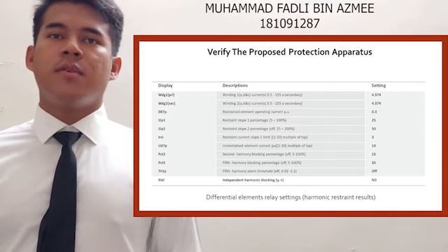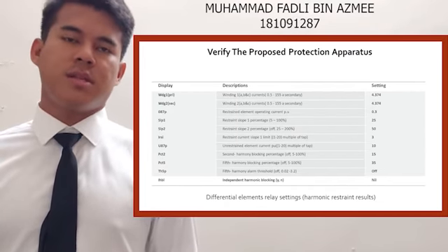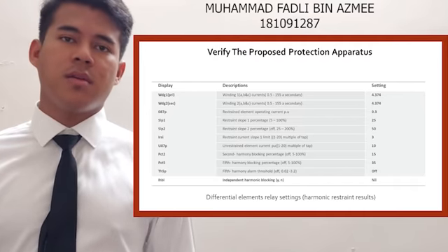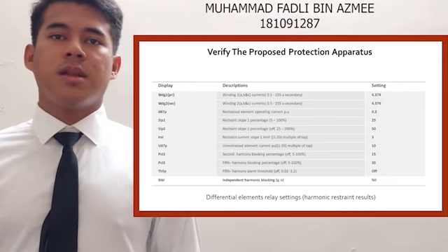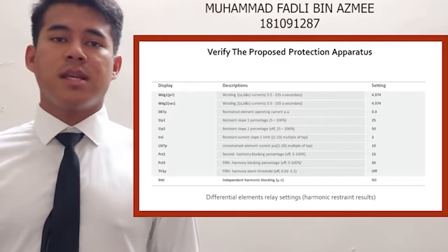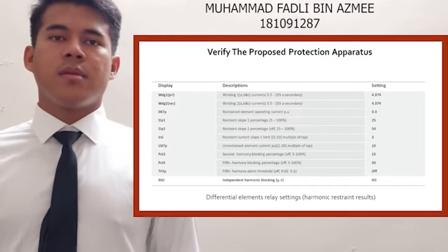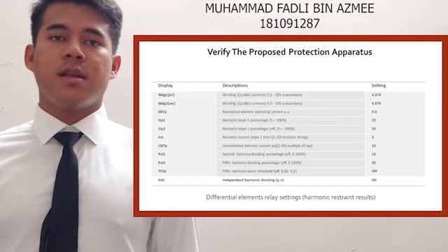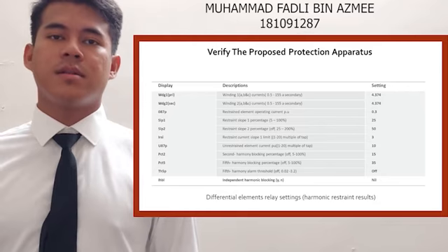So, there are a few highlighted advantages of microprocessor-based differential relay protection. The first one is high stability against inrush current due to the advanced filter technology and optional cross-blocking function. High stability against over-excitation, which is the fifth harmonic blocking. Short tripping time, typically 1.5 cycle. And lastly, high-set fast tripping, less than 1 cycle.